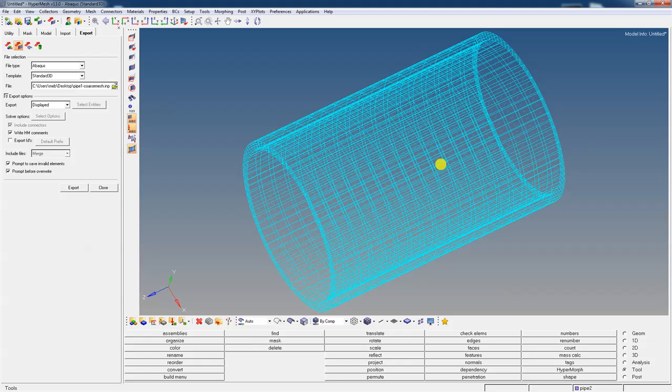Alright, so what we'll do is we'll bring those into ABAQUS. We're going to do some heat transfer analysis, and one of the things I want to do eventually with this is I want to show you how you can do an interpolation scheme if you have mismatched nodes from one mesh to another. Like maybe you did your heat transfer analysis with a very fine mesh, and you want to extrapolate or interpolate the nodal temperatures to a coarser mesh. I will show you how you can do that. But for now, this is good, and we'll pick this up at a later time with ABAQUS.